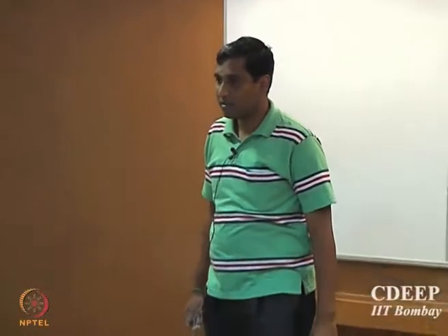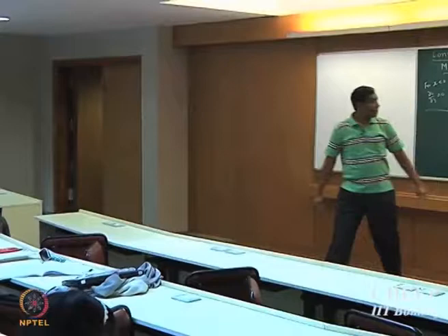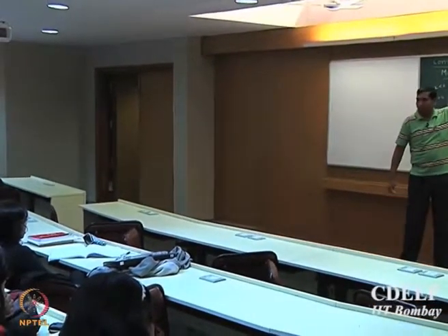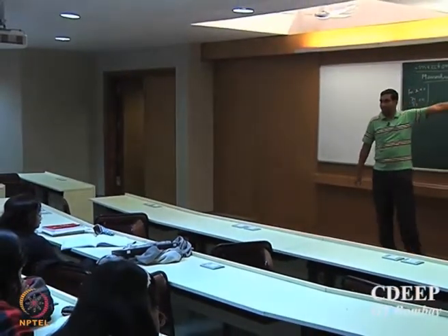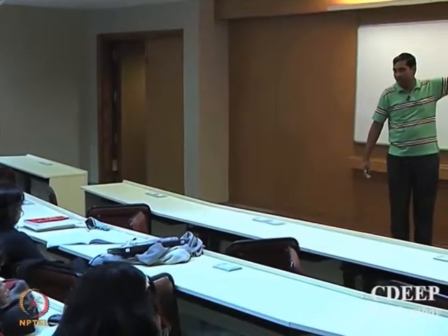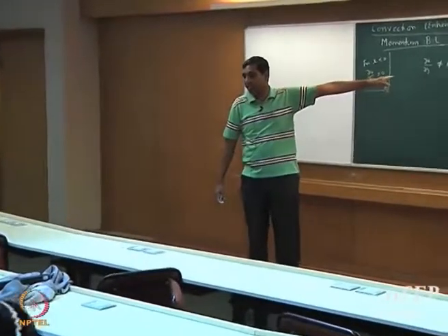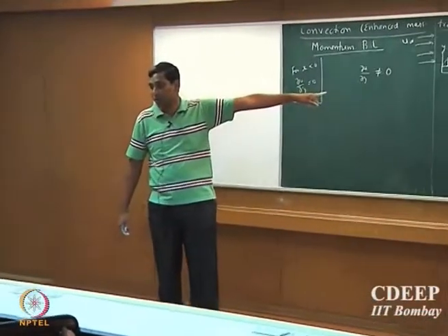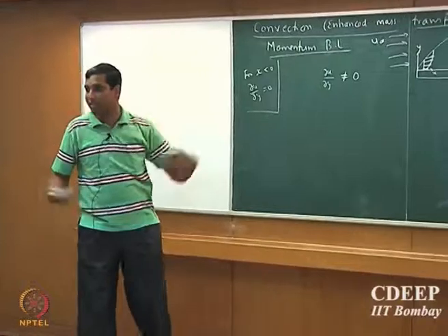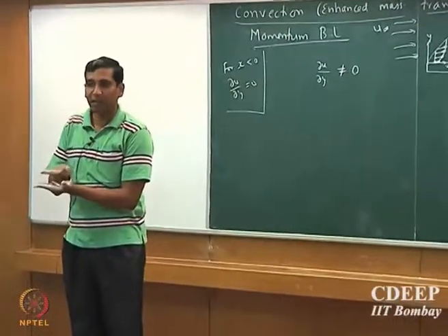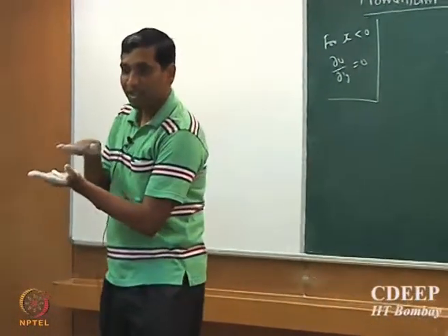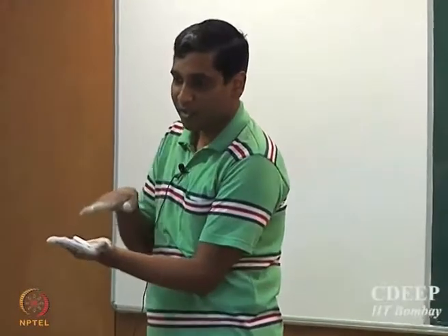It has a viscous shear. We are going to talk about shear stress very soon, but note that it has viscous effects. Because of viscous effects, the gradient is going to come in both directions. And why does it retard? Because there is a definite viscosity, so when one fluid particle is at rest, the other fluid particle is trying to flow at a certain velocity, but it is going to offer a retardation because of the viscosity.